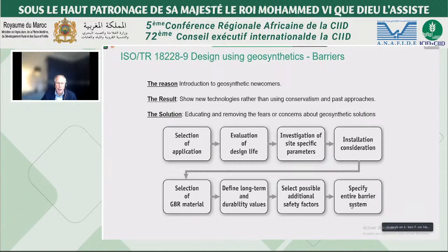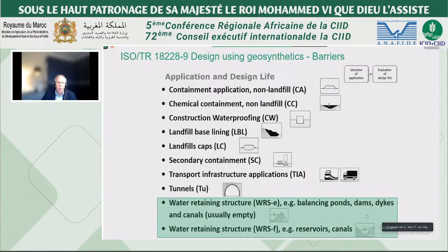But all the others who are new, the young students, might not know how to design. It gives you a guide on how to select the application and the design life, select site-specific parameters, look at the installation, then select the geosynthetic barrier material, define durability, add safety factors, and then specify the entire system. So it's not a calculation tool, it's a guide. How do you get from the beginning to the end? And just to give you a brief overview, it contains all applications with geosynthetic barriers.